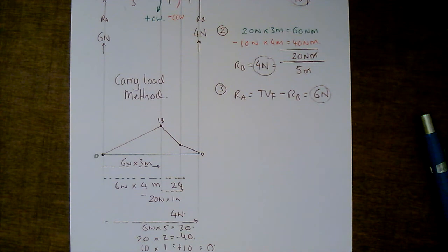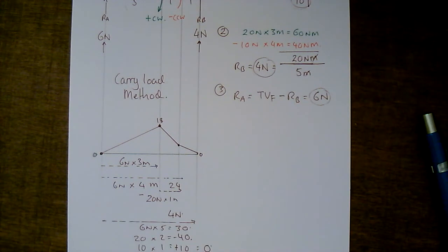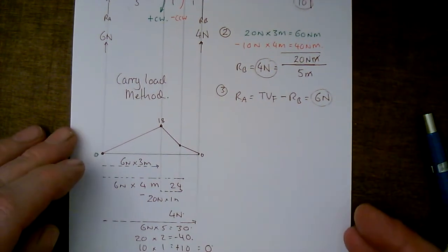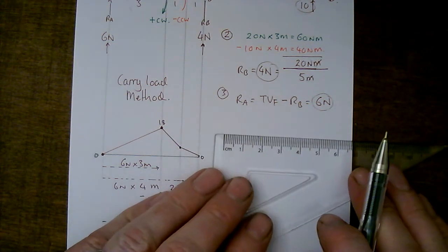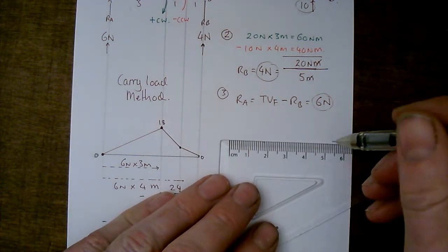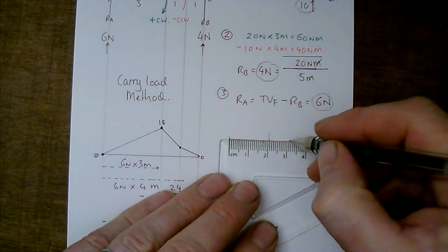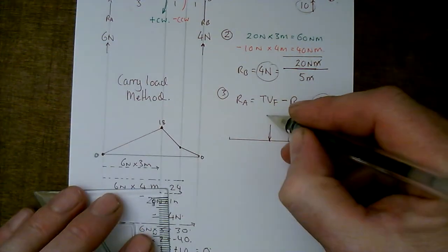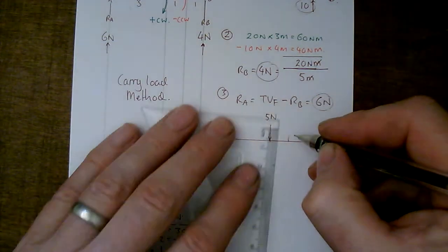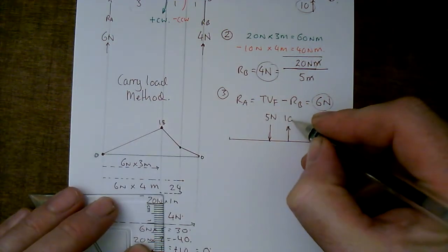And that's a quick introduction, if you will, to a bending moment diagram, similar to something you might encounter for a Cambridge technical examination question. And it's worth just, like I say, you can set these up and randomly practice. So I'm going to put one here for you to have a go at. So let's do 5 meters, at 2 meters, and at 3 meters. I'm going to give you a downward force, 5 newtons, and I'm going to give you an upward force of 10 newtons.